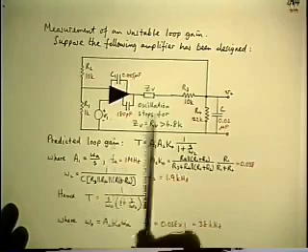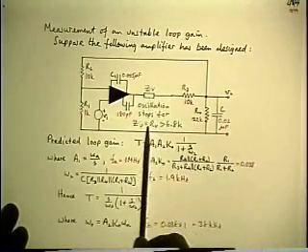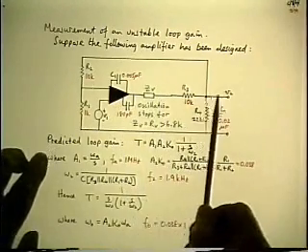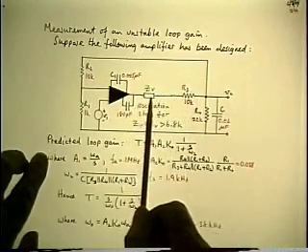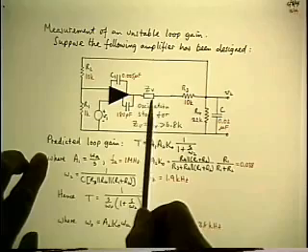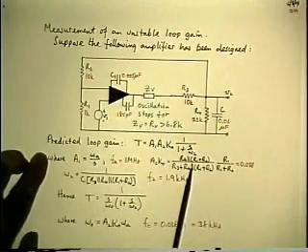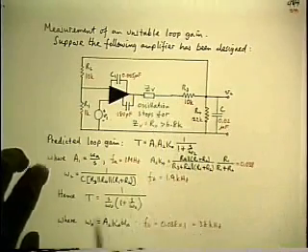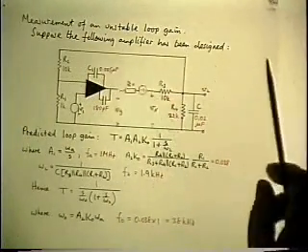Now, that still may seem a little surprising, but let's follow it through. I actually did this. This was sitting here oscillating, and so I take a few resistors and I start sticking them in, and 2.2K doesn't stop it, and 3.3 didn't, and 4.3 didn't, and 6.8 did. So I went a little further. Doesn't matter. I put 10K in there. Now it's quiet. It's stable.